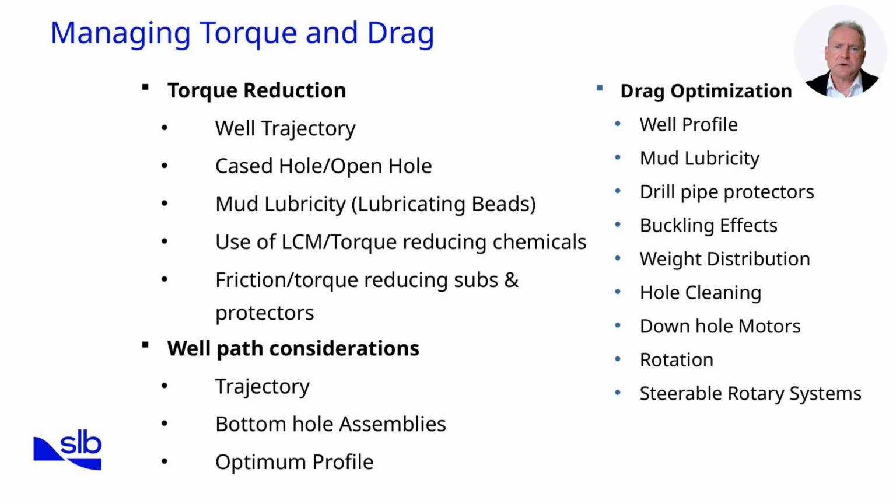Keep in mind, whatever you physically add to the string has a pressure drop and may cause hydraulic limitations. Also, they may break and become junk which has to be fished.